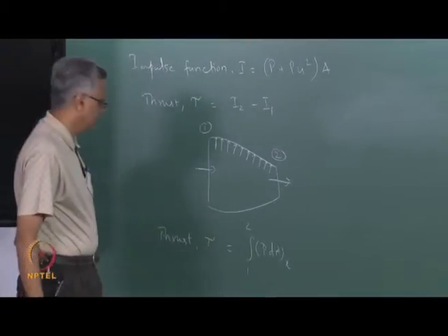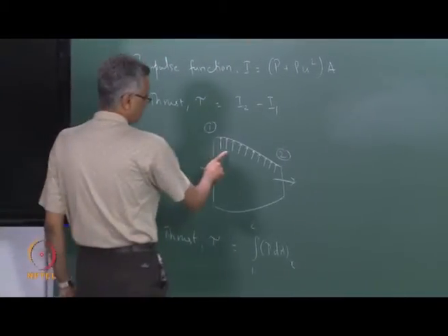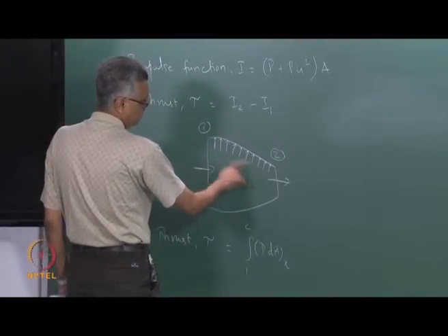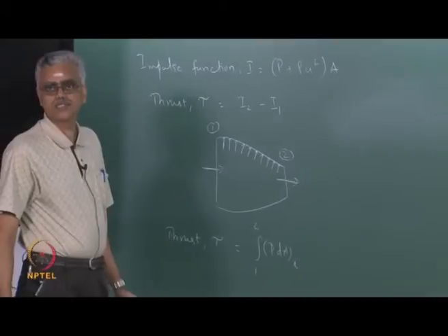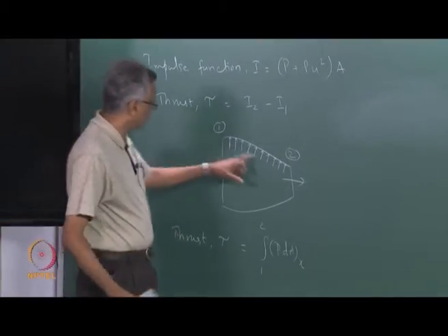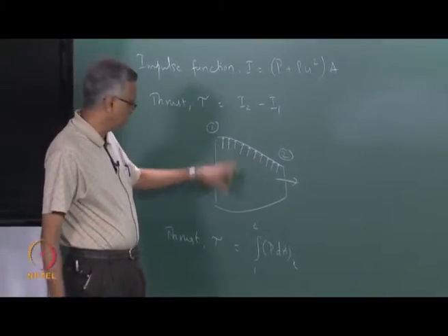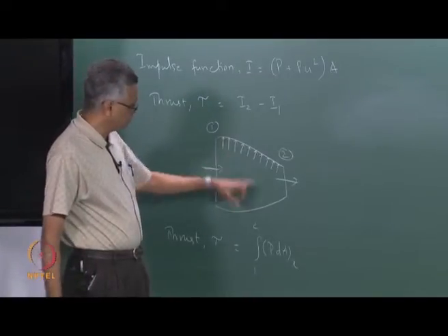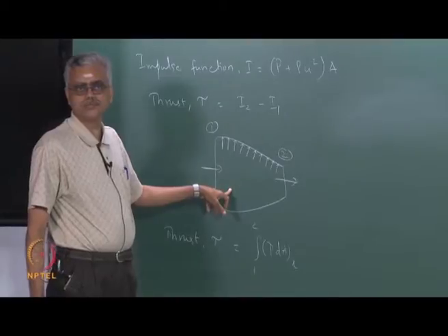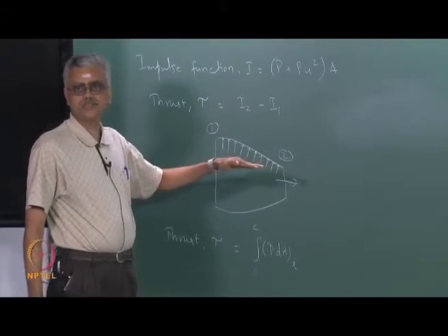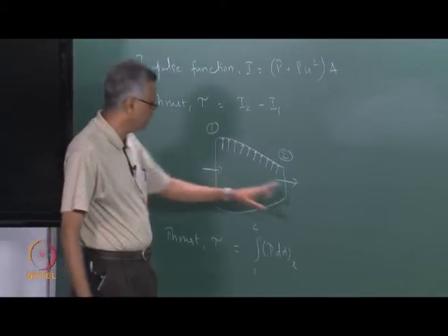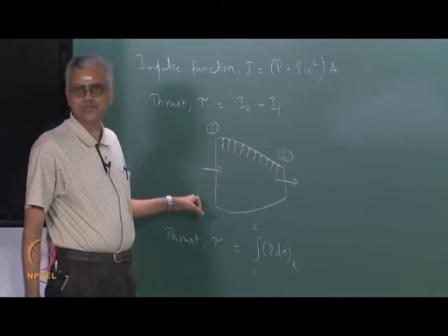It is very important to remember that, and the pressure decreases as we go along the length of the nozzle, because the flow undergoes an expansion process. So, if you take the x component of the pressure force on the top and the bottom side, you will realize that the net force exerted on the nozzle is in the positive x direction, which means this is actually a drag force and not a thrust force. So, even if you evaluate I2 minus I1, you should get the same thing.